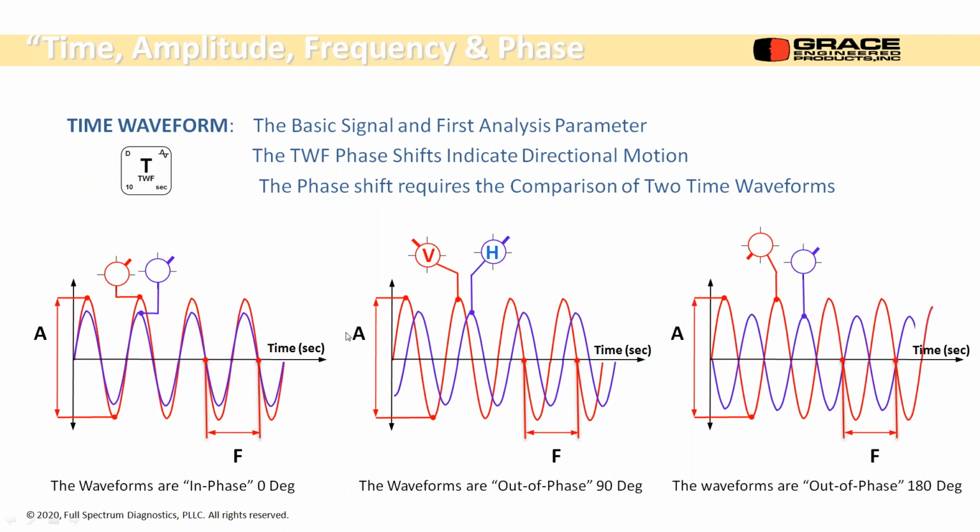Okay. All of these occur at 1 times RPM, or potentially can occur at 1 times RPM. So unless you had phase, you wouldn't be able to decipher the difference between them. And that's why we use it. So pretty important.